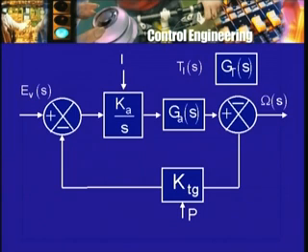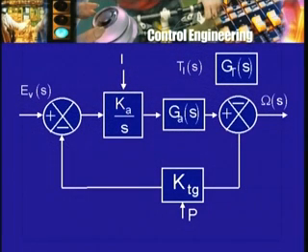And now we want to study the effect of Ka, this gain of the amplifier integrator, on the transient behavior of the system. We saw that it plays no role in the steady state behavior of the system. The steady state speed is simply such that ER equals K tacho generator into the steady state speed, irrespective of what the load torque is. So the motor will run at the desired speed irrespective of the load torque changes. So in the steady state there is no problem.